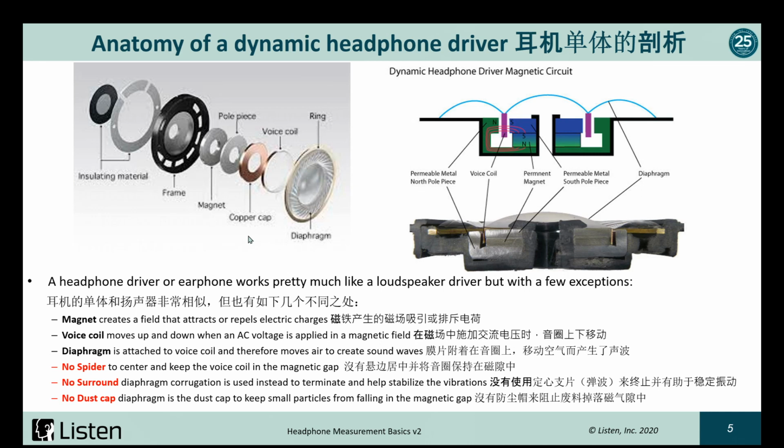But one of the things that happens, unlike with conventional speakers with dust caps, where you can have soft domes, is that typically the diaphragm in a headphone speaker is quite rigid. And if you're not careful, if you get a wrinkle or a little crease in the diaphragm, you can create a buckling motion and get a sharp snap. So that's one of the defects that you've got to be a little careful of when you're creating the earphone driver diaphragm. I've been able to pick that up on a production line with loose particle detection.